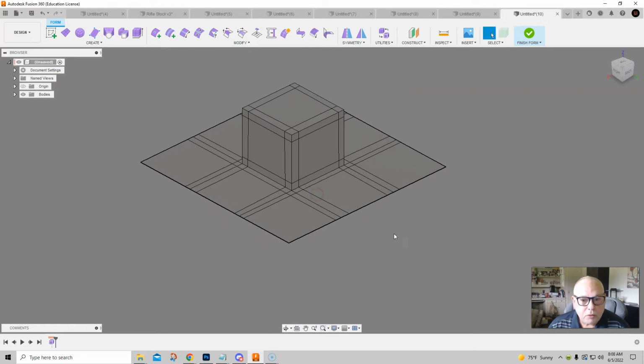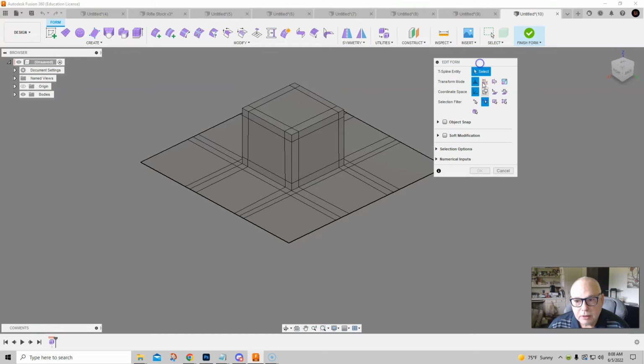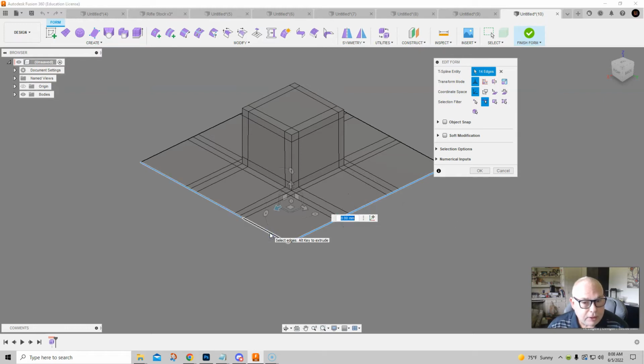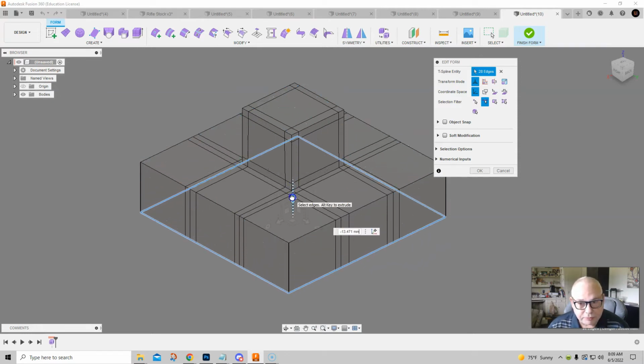Okay, so we can also do our edges, so we can double click here. Now, by the way, if I hold down the Control or the Shift, you can add to it. So it could be Shift or Control, and then Shift or Control, double clicking on it again will deselect. All right, so I've got all those. Hold down my Alt key, and I can drag straight down.